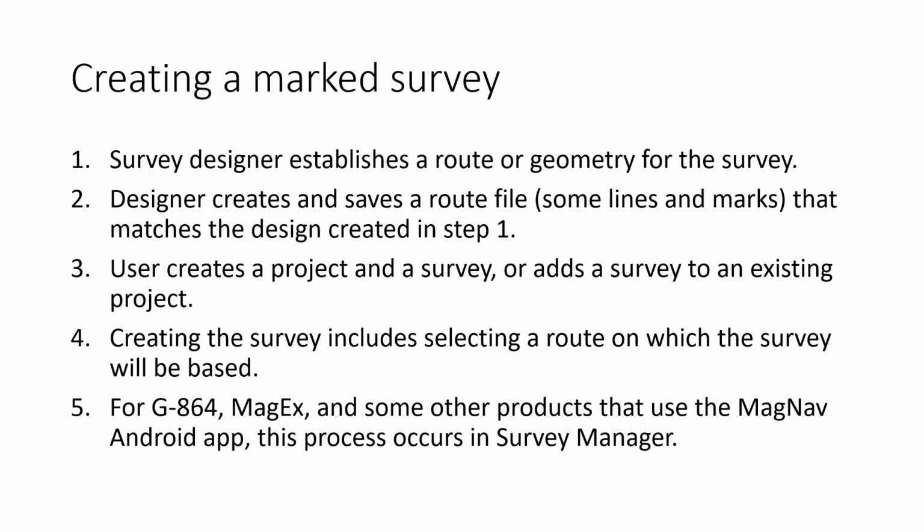Your survey designer may look at a site and say, this is a 100 meter by 100 meter survey area, and we'd like to survey at 1 meter intervals or 2 meter intervals, and we may have a certain number of waypoints along each line that spans that area, and so on.